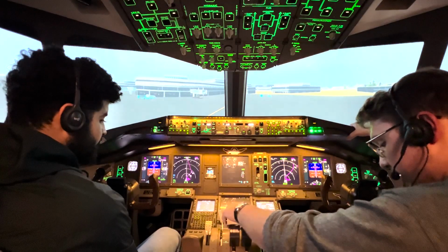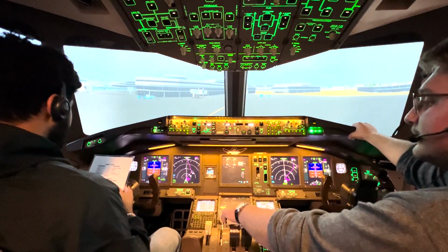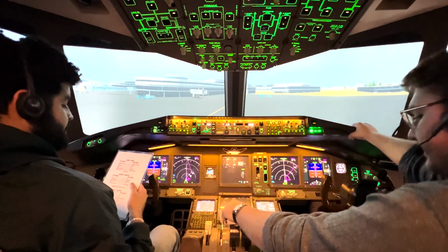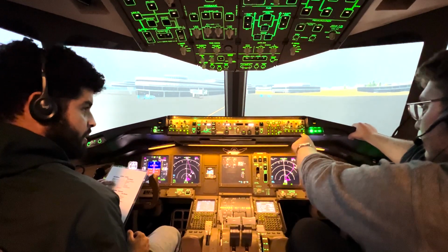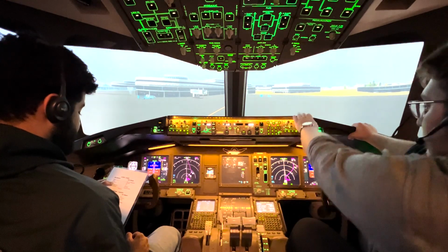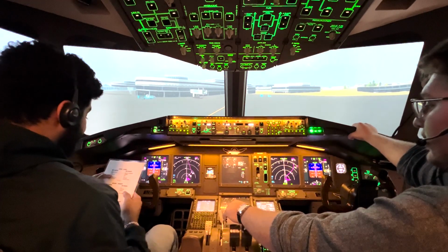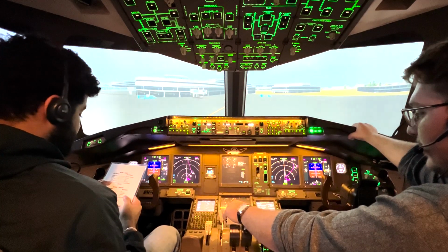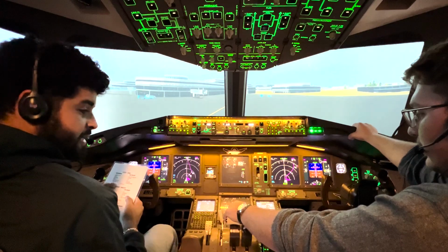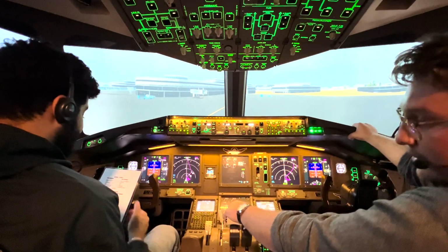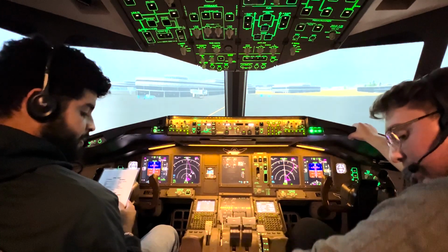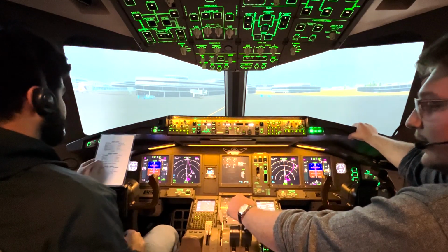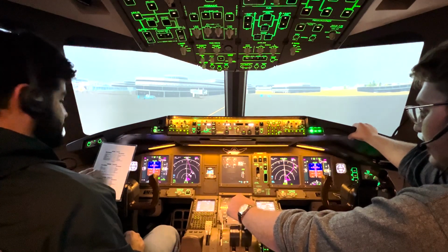Okay. The after start checklist, please. Engine anti-ice, and wing anti-ice auto. Recall. Recall checked. No warnings. Auto brakes. RTO. Flaps. 5 in green. Final load sheet. Loaded. Flight deck door. Is still open. Now it's closed and locked. Perfect. Taxiing.